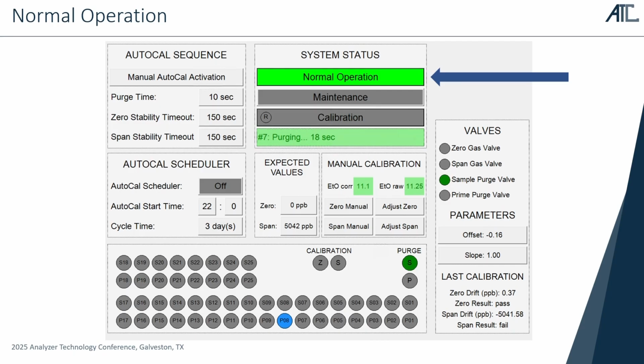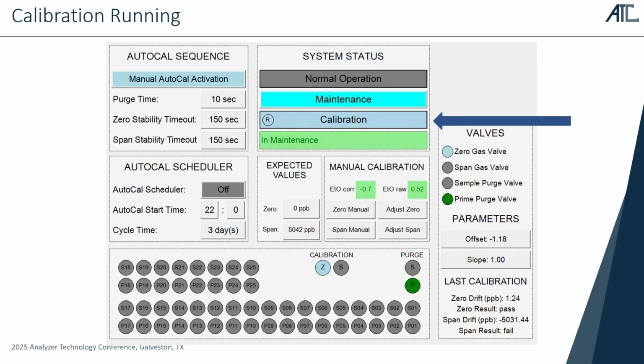And the calibration happens should you fail any validations. Now the analyzer is out of control, the data is invalid, that's affecting your data availability. So then, based on the 0 and span factors, you would do an adjustment to the data to calibrate the analyzer and bring it in line with those values for the data to become valid again.